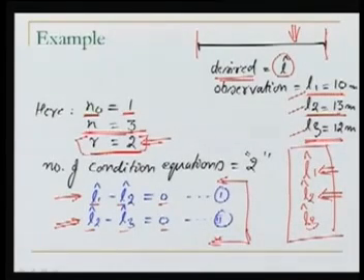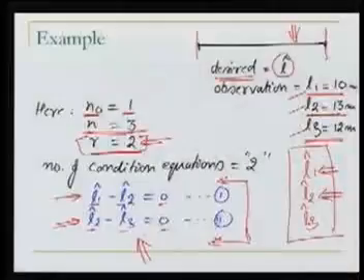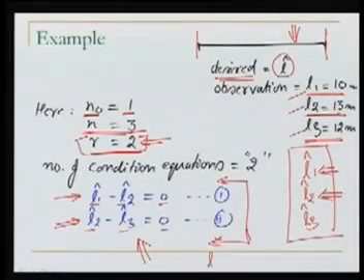And this is important. The very first step of writing the conditions is very important. We are writing L1 hat minus L2 hat is equal to 0 because both the observations are adjusted. If they are adjusted, these should be the same. Well, having written it, next step we know we need to replace L hat with L plus V. This is what we are going to do now.